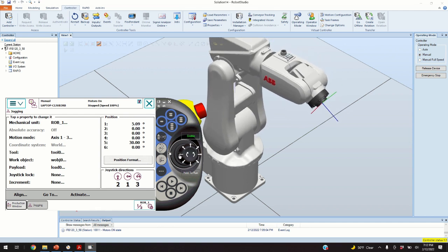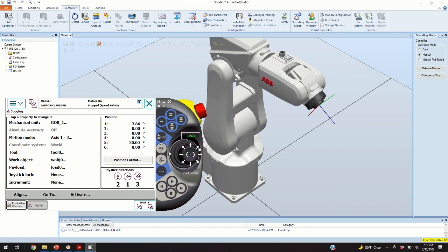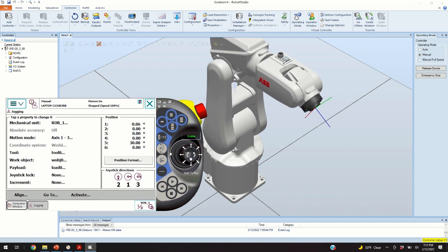And how I know that basically by moving joystick in this direction I will be able to change these values of the first joint? Well, I can see it over here. So this button tells me that left and right buttons are moving the first joint, that is the base joint. So I will set this value to 0, since this is my reference configuration. You can press it and you will get a 0 position.